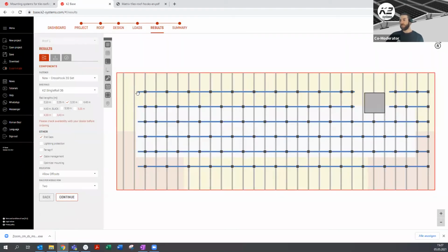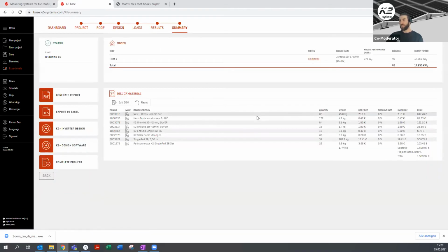And now you see we are using way fewer roof hooks. So it's just every second rafter, and obviously sometimes it's double because then it switches off. But in total, we are using 86 now instead of 156, or I don't remember the right amount, but something like this is nearly half the amount. And even if the CrossHook, which is made out of aluminum, is a bit more expensive, a little bit pricey, not much, but then you need half the quantity, you still get way cheaper on the whole project.